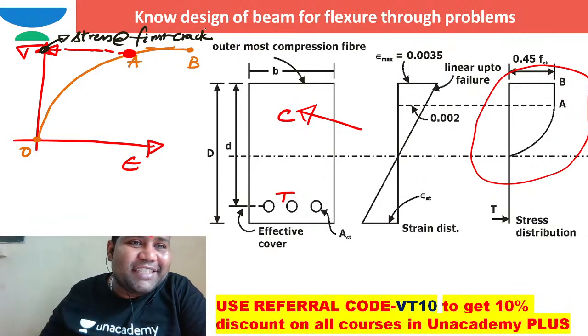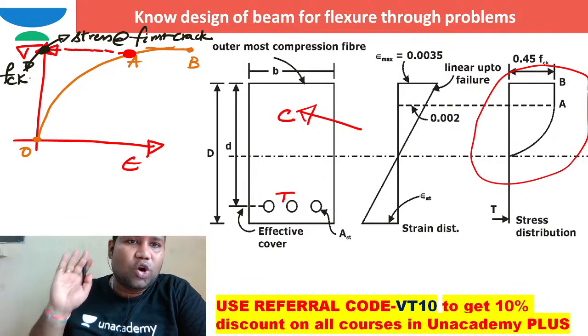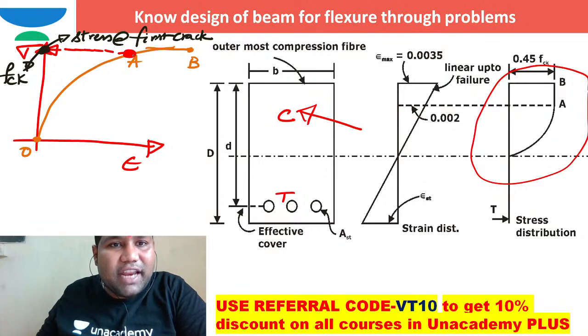So indirectly it is nothing but the actual failure strength of concrete. Indirectly I can call this strength, definitely, FCK, no doubt. Now, even after the first crack there is a little increase in strength, maybe 5%, maybe 2% or something like that. A little increase in strength is there.